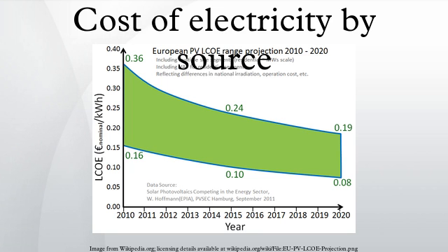By comparison, when a new plant is being added to a power system or grid, the effects are quite complex. For example, when wind energy is added to a grid, it has a marginal cost associated with production of about £20 per MWh, and therefore will always offer cheaper power than fossil plant. This will tend to force the marginally most expensive plant off the system. A mid-range fossil plant, if added, will only force off those plants that are marginally more expensive. Hence very complex modeling of whole systems is required to determine the likely costs in practice of a range of power-generating plant options, or the effect of adding a given plant.